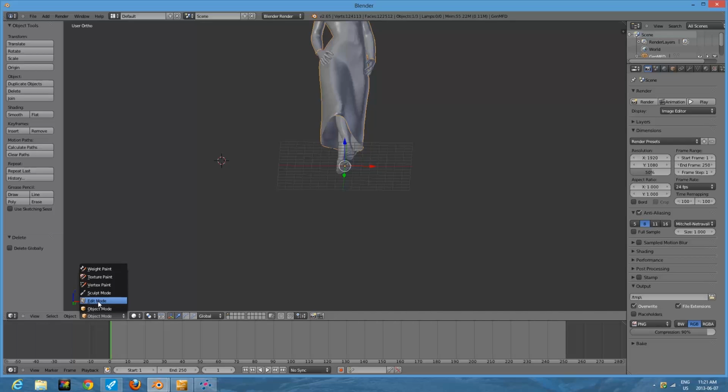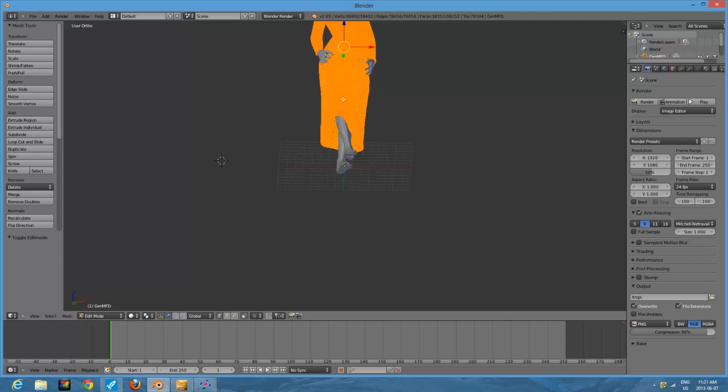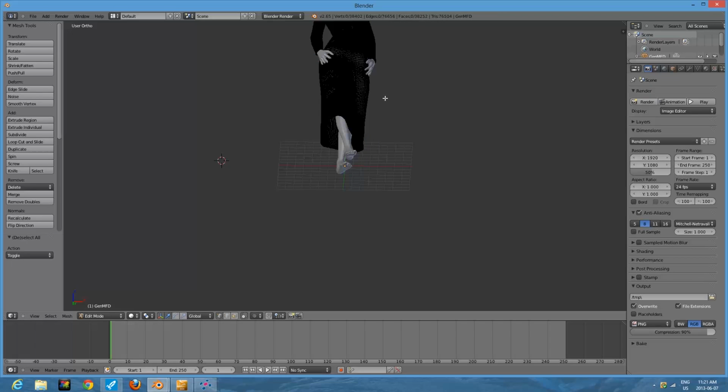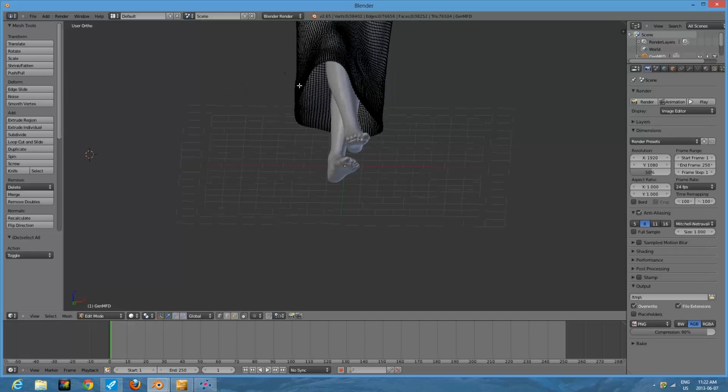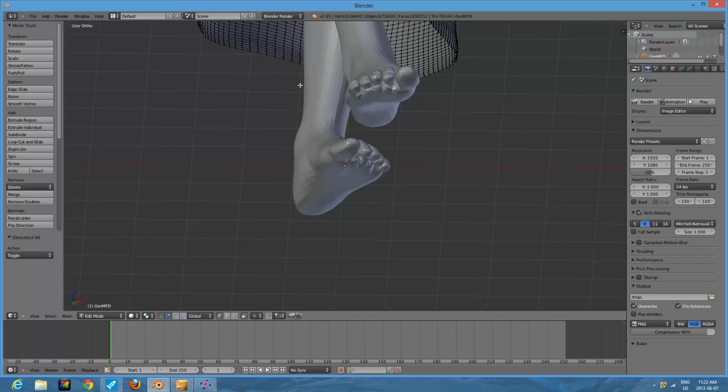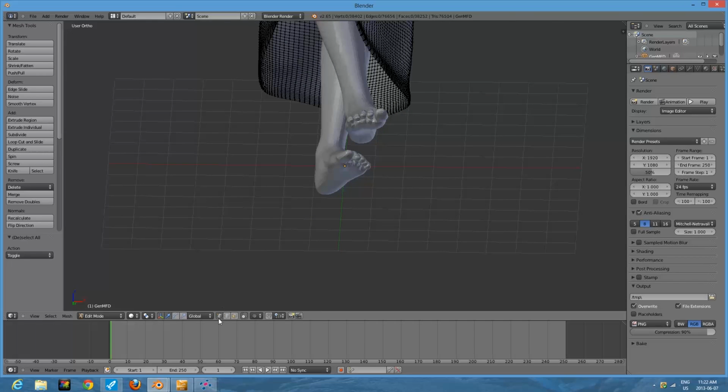in edit mode. So just click down here, and you're going to notice it turns into a bunch of orange dots. It's because it was highlighted. If you hit the A button, it will select and deselect those dots. These dots are called vertices, and a mesh is made up of vertices that are connected by lines. Right now we're on vertices selection mode, so if I right click anywhere, it's going to select the closest vertex. Okay. You also have line selection, which is the one we're going to be using here. And then face select.